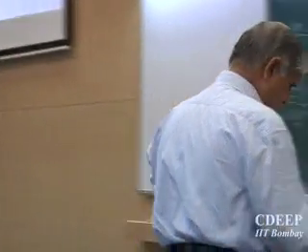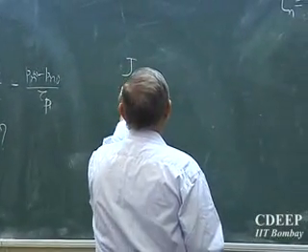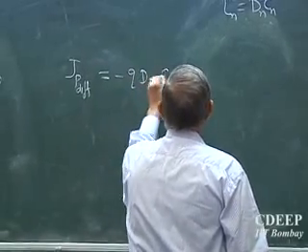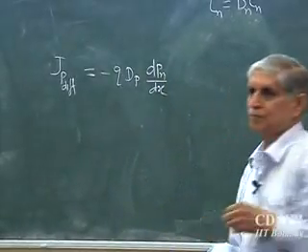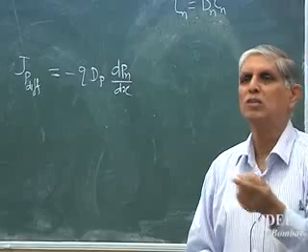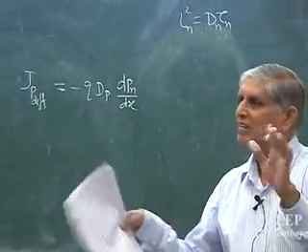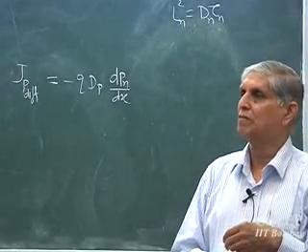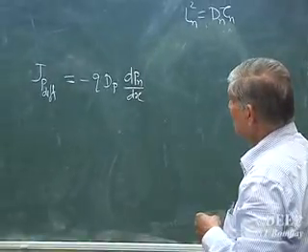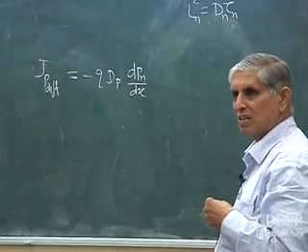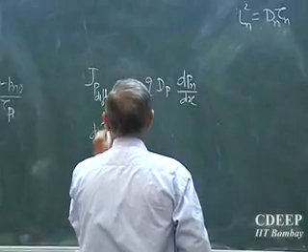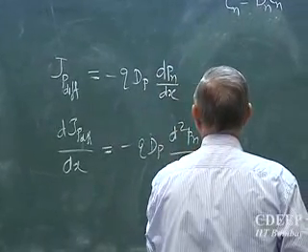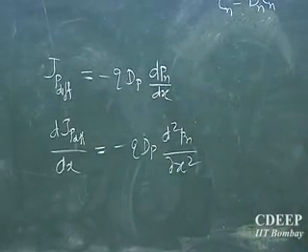So we start looking for what is the Jp term, the diffusion term actually? Jp diffusion = minus q Dp dp/dx. I am keeping that n just as a caveat that this holds in n-type. If I don't do all of that, I can just write p and n normally, but since we are looking for minority carriers, we keep writing that they are minority, p's in n. Okay, so if I have this, can I use this equation to substitute something there? I differentiate this, so I get dJp diffusion/dx = minus q Dp d2pn/dx square. Is that okay?